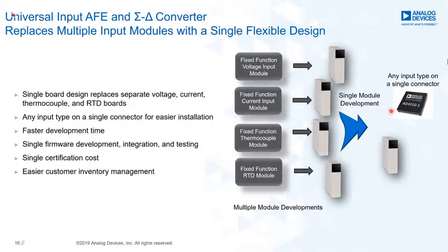We are giving you this particular chip, AD4110, which has all the necessary mechanisms built into the chip, and that can be configured over SPI for any of these inputs. That way, you will have a single hardware addressing all your industrial inputs. Hence, it's a universal AFE handling all industrial inputs.